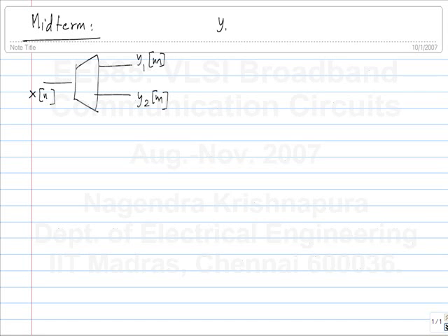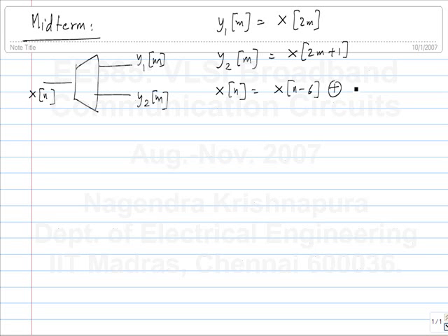And I said this is pretty obvious. This is just the definition of demultiplexing. You get the even stream in one and the odd stream in the other one, and X itself is generated as a pseudo-random sequence. In this particular case I am taking PRBS 7, so I take the 6th and the 7th previous inputs, XOR them and form the next value of X.